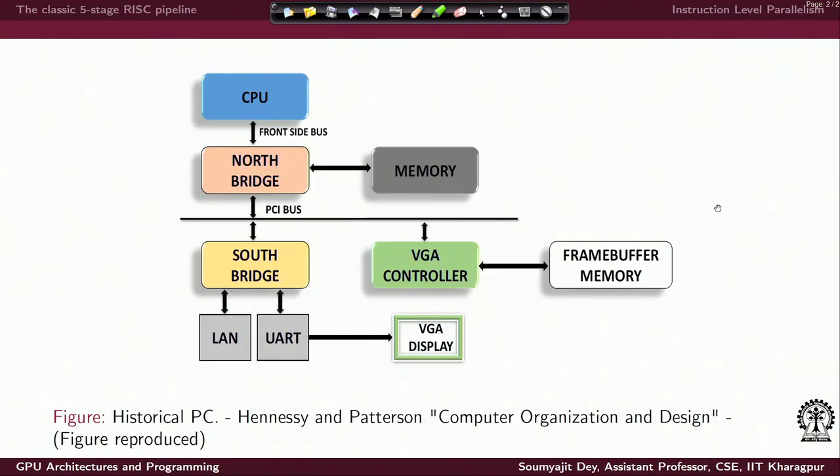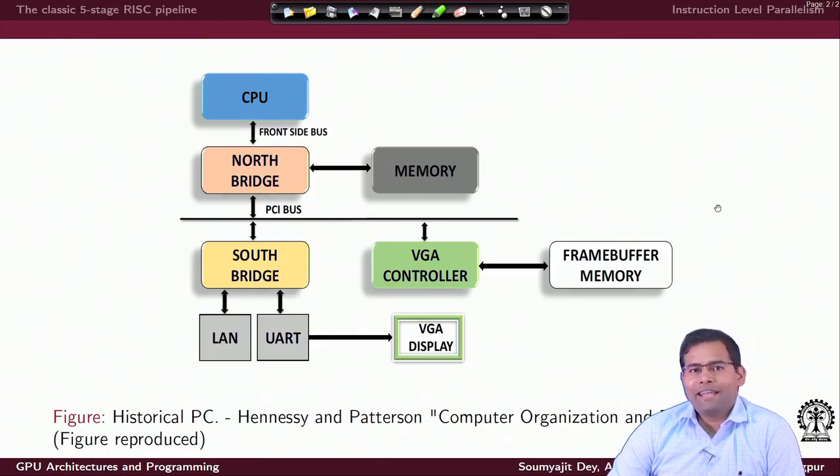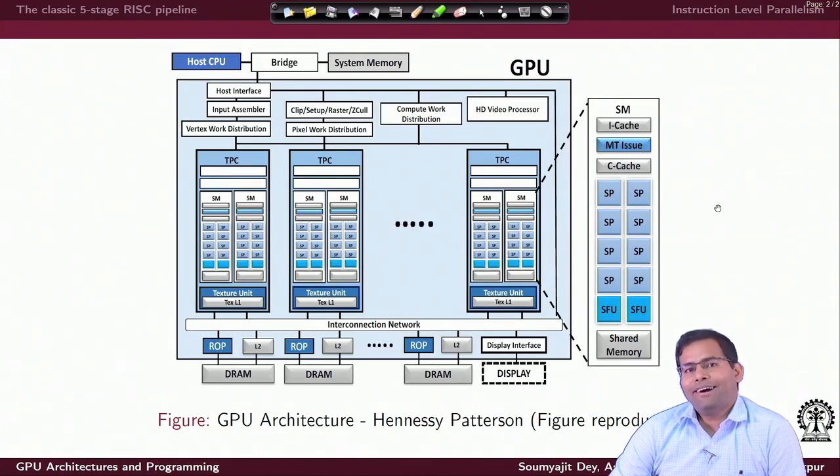And we also provided this snapshot of how a standard CPU connects with the VGA and other related peripherals, vis-a-vis how really the architecture of a GPU looks like, with a lot of processing cores inside it, which are the SPs or the scalar processors. This is just to give an idea that I can view a CPU as maybe a multi-core platform containing a small number of compute cores, whereas a GPU essentially contains thousands of compute cores, though simplistic in terms of functionality, but lots of them.